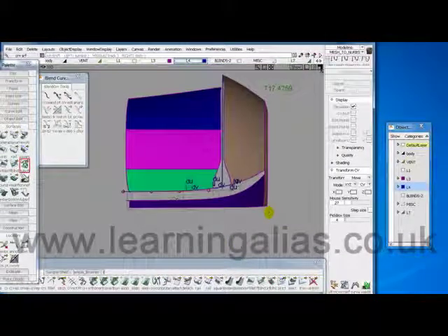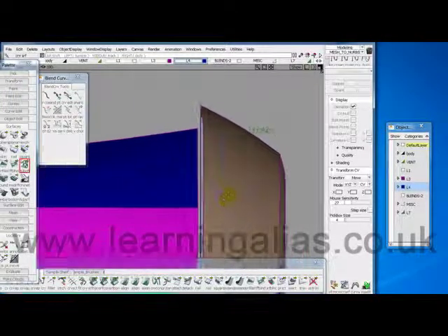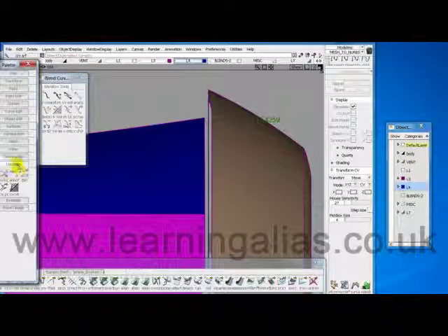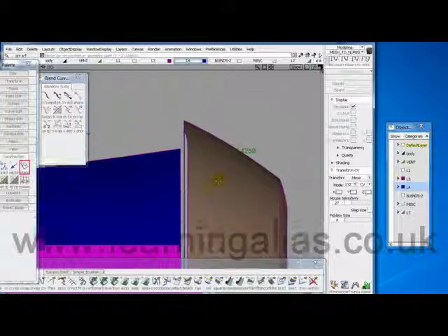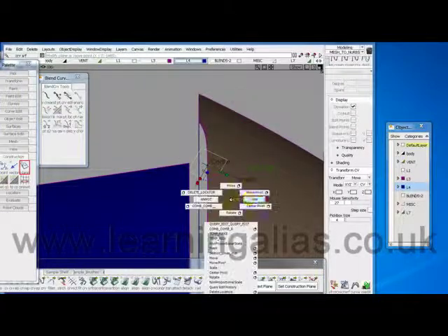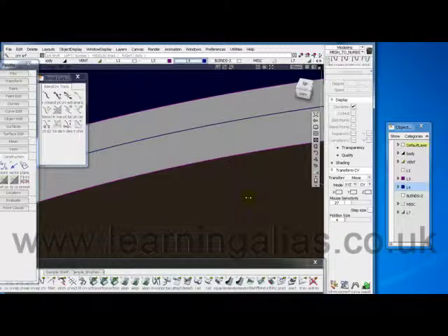Okay, and we're ready to build our transitional surfaces there. And the best way to do that is with using blend curves and using construction planes. There are shortcuts, but in my experience shortcuts take 3 times as long in the long run. I sound like a bit of an old timer, don't I? Here we go then. So just put your plane on there, and I'm going to scale it until it touches that point there. If you're not sure, go into F8 to get a better look.